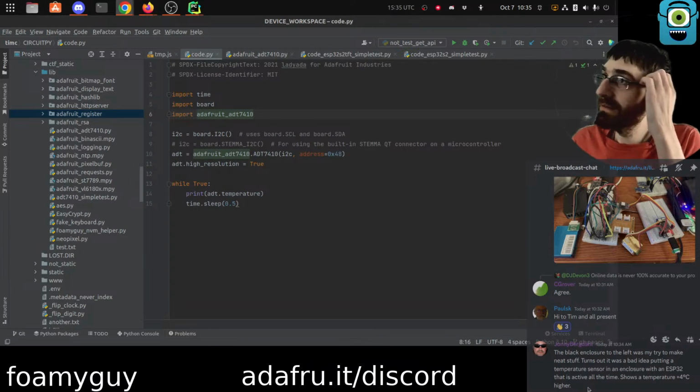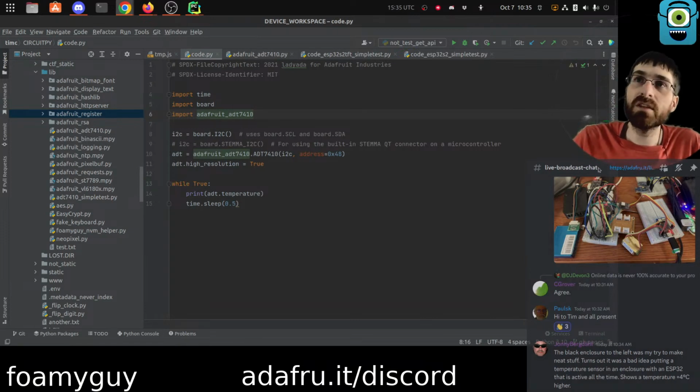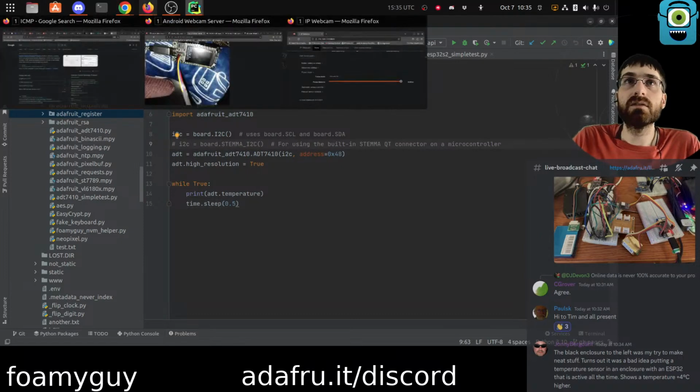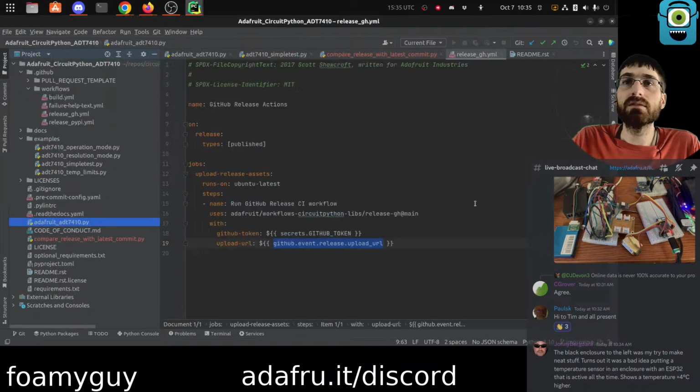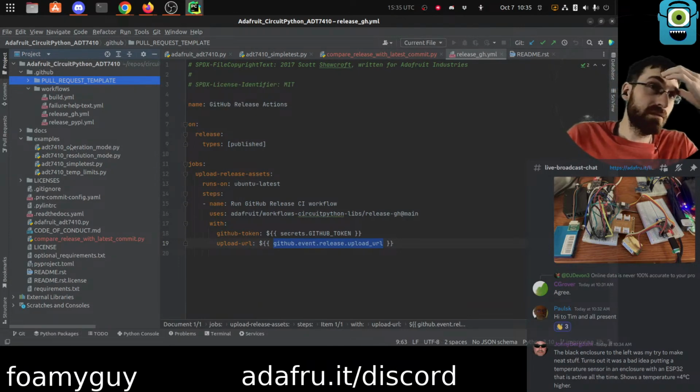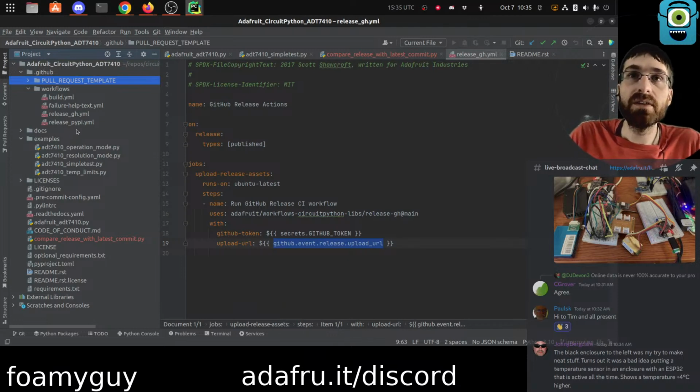Yeah, with temperature sensors in particular, for sure the casing is a tricky business because, like you noted, if it's enclosed in there, the microcontroller is probably going to run hot unless you have a super special microcontroller or you have some heatsink action going on. Even the heatsink is not really going to work though, right? Because you're heat sinking to the air, so the heatsink is just trying to get heat off the CPU, but you're putting it into the case that your sensor is inside of.